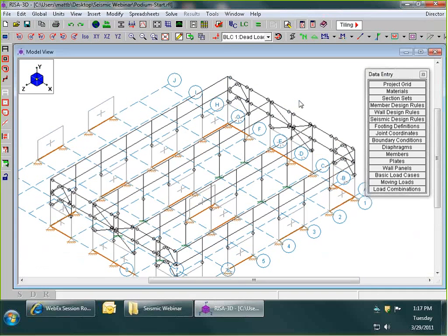seismic resistance. Now, clearly, because we have so many moment frames running in each direction and so many brace frames running in each direction, the failure of any one of those frames is not going to cause an overall failure of the structure. So therefore, we can be justified in using a rho of 1.0 for this structure. So that's what we're going to go ahead and do.